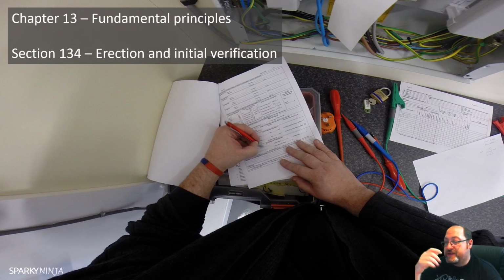The equipment shall be installed in such a manner that the design temperatures are not exceeded. So we need to understand the design temperatures. That's the temperatures, obviously, with regards to the equipment under load, with adjacent equipment under load. This can become a big problem because I see an awful lot of electricians take pictures of their new work, and there's a lot of habit these days where people cable tie their cables all together, and there's grouping. Grouping is becoming a big problem. People aren't understanding design temperatures because maybe they're not being told them. Equipment likely to cause a high temperature or electric arc shall be placed or guarded so as to minimize the risk of ignition of flammable materials. We'll cover that in chapter 42, protection against thermal effects.